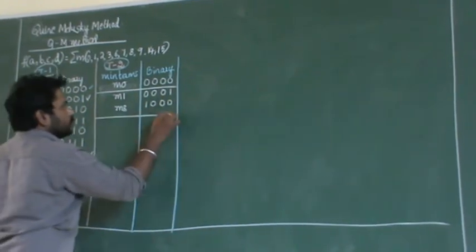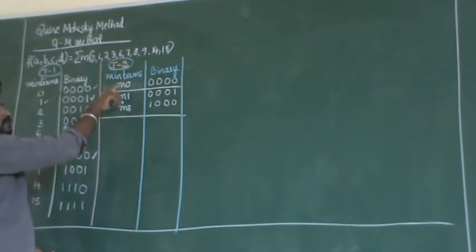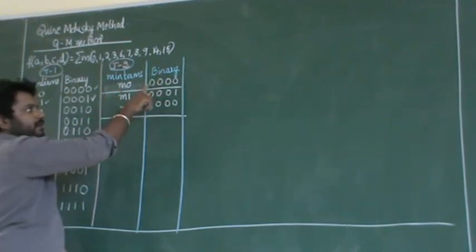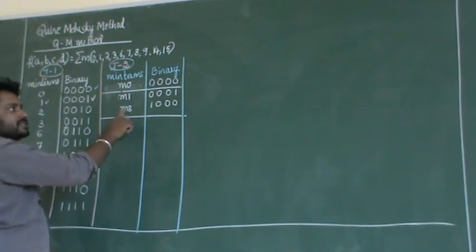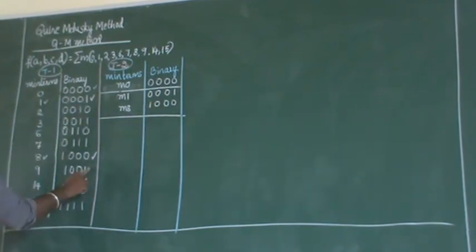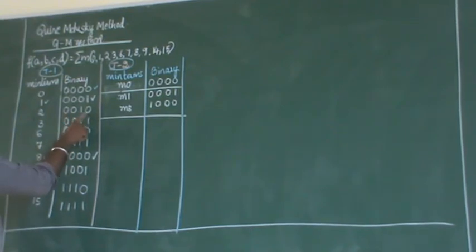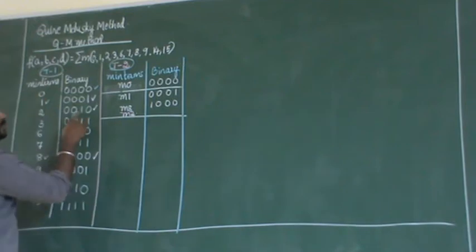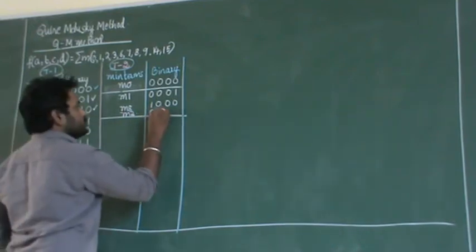This is the first group, which is having only a single term, which is having no ones at all. This is the second group, which is having a single one. So I have written 3 terms, and again I think I can write M2 also, which is having a single one. So therefore 0, 0, 1, 0.